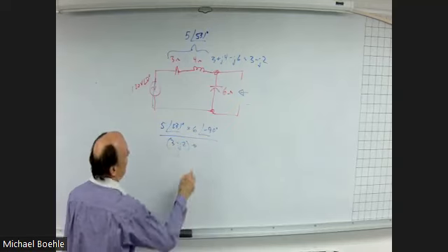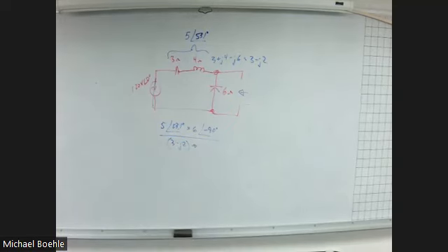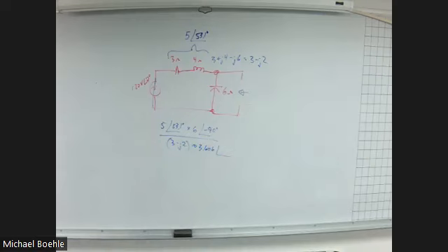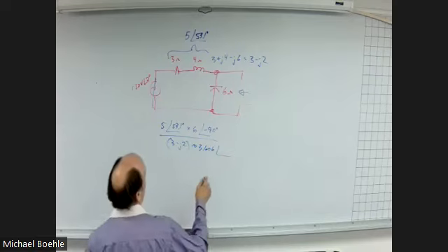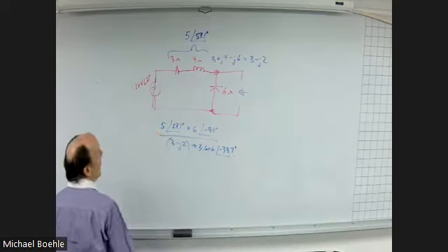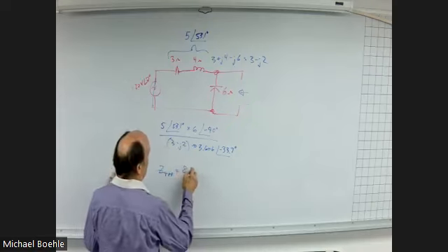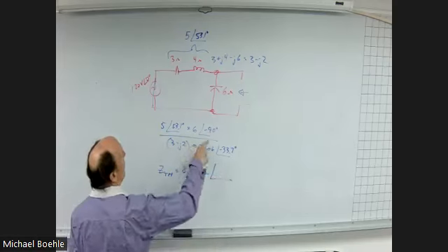And of course, that's in rectangular form. So when we convert that to polar form, you have the square root of 13, or 3.606, at an angle of the inverse tangent of negative 2/3, which is minus 33.7. 5 times 6 is 30, divided by 3.606 is 8.32 ohms at an angle of, let's see, 53.